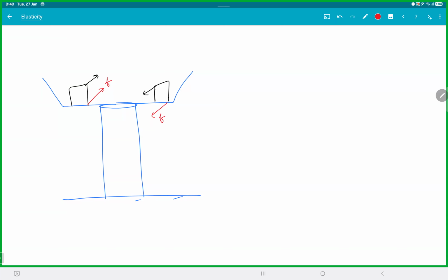Can you see what is happening? Whenever the trains go left and right, they're producing a frictional force about which there is a torque. That entire section is trying to rotate. The pillar is getting a twisting force. So every time the train goes, the metro pillars are twisted. They're trying to twist. We don't let them twist. And this happens every day. How many times? If the trains are doing, let's say, 400 trips, every pillar is being twisted 400 times per